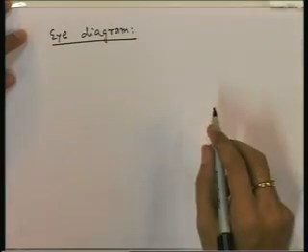An eye diagram is a graphical illustration of ISI. How do we get that? It is a graphical illustration which will give us some impression about how much ISI is there. So, how do we get ISI? Simply by taking the output of the receive filter.